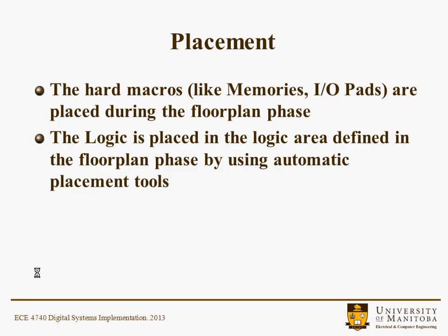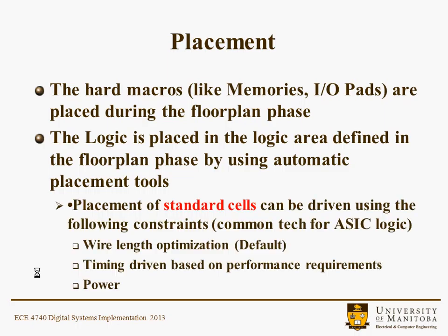So this is the hardware that you basically are specifying as a netlist that you want to get implemented in silicon. If it's a placement of standard cells, it can be driven by a number of different constraints, such as perhaps minimizing area, minimizing wire length, and more recently timing-based specification. So you may have to take into account that even though you get a really nice compact design, there may be one net in it that is causing you a performance problem, so you may have to redesign it, or it might be too power hungry, so you have to change the way it's implemented.